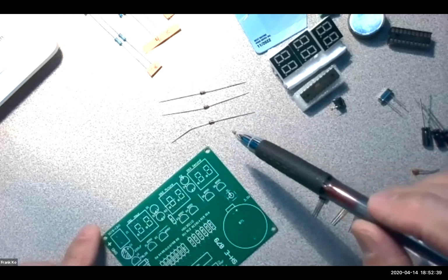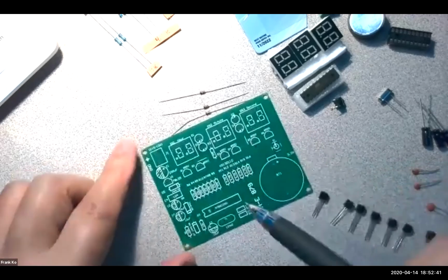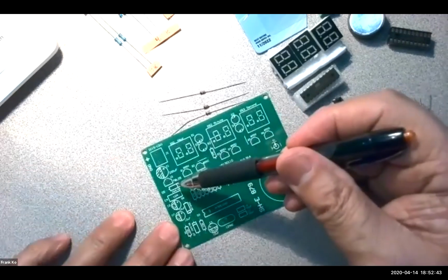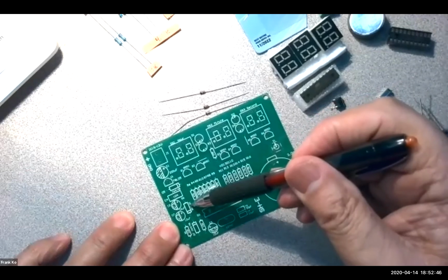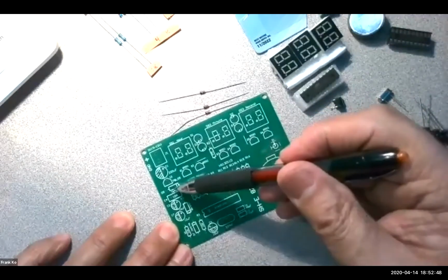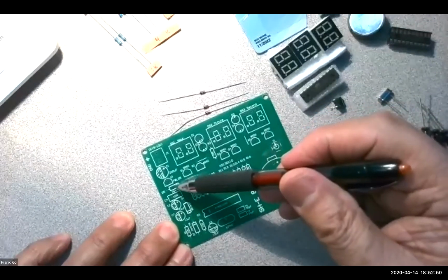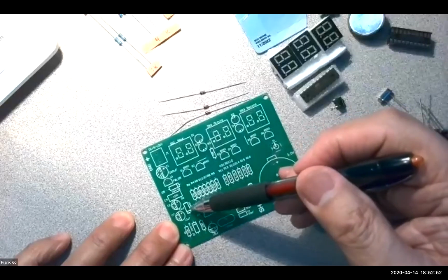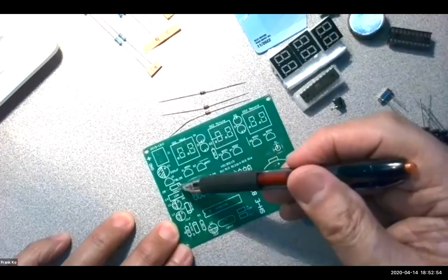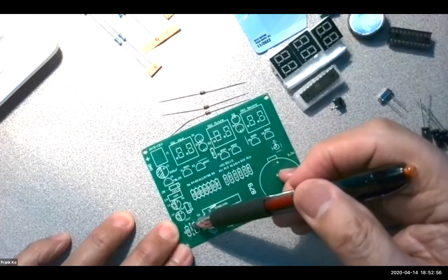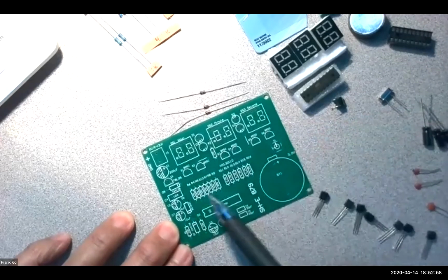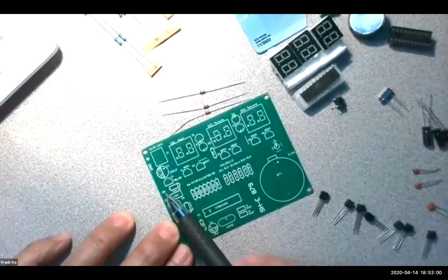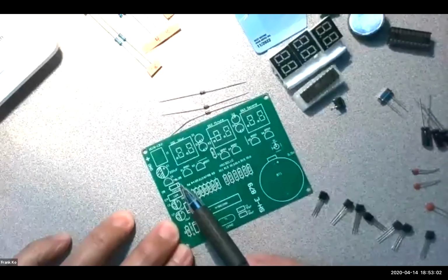So where do these diodes go, the 4148s? So the 4148 is identified here, and identified here. So 1, 2, 3. So diodes D6, D5, and D7 are marked on the board 4148s. And you can tell also which side of D5 is supposed to be the cathode.